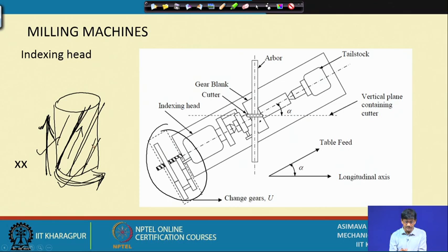So, this is what is done. We put a gearbox here which establishes a definite relation between these two depending upon the requirements. The requirements might be to cut a 15 degrees helix angle on a gear. I mean, cut 15 degrees teeth on a helical gear. For that, a definite gearbox will establish a particular relation between the longitudinal motion and the rotational motion.